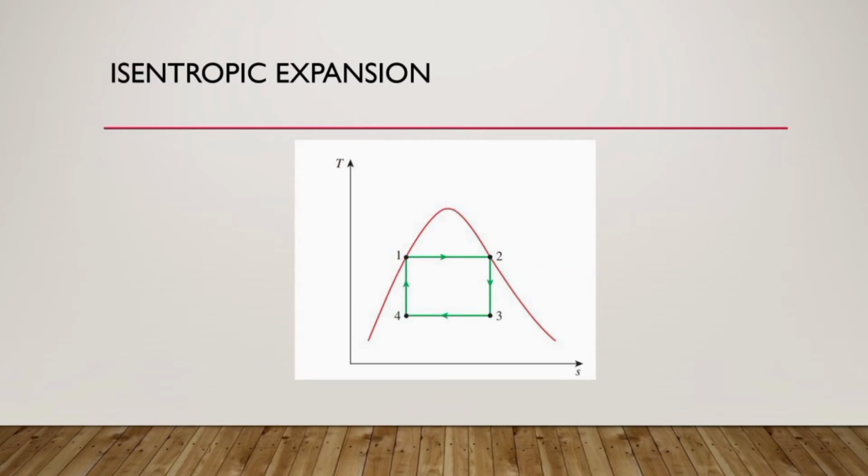However, as you can observe from the graph, there is a significant decrease in the quality of the steam along the process. This means at some point the turbine will handle low-quality steam with high moisture content, so water droplets will form on the turbine blades. This will most likely cause the turbine blades to erode and eventually become a major source of wear. Steam with quality less than about 90% cannot be tolerated in the operation of power plants.